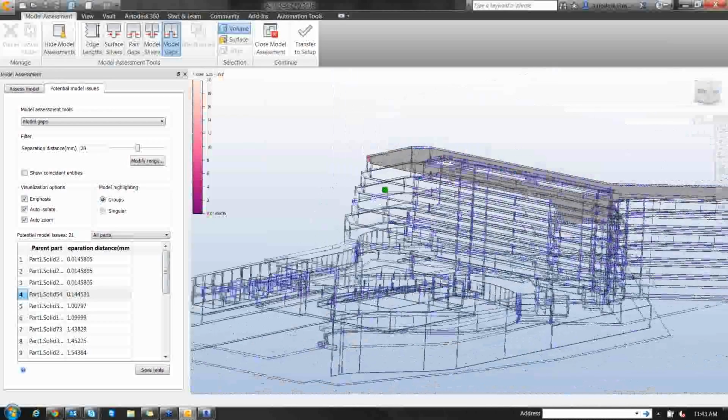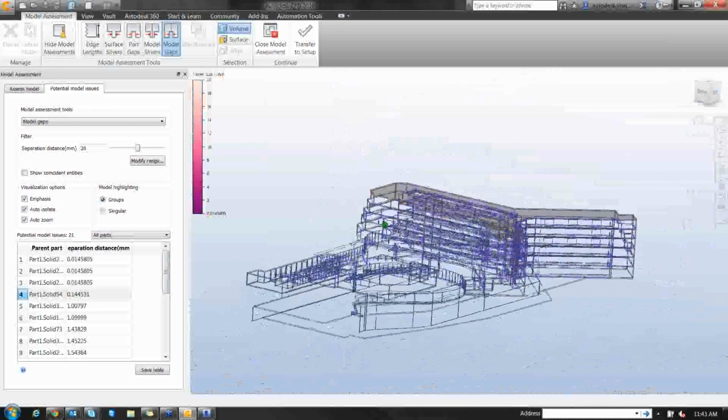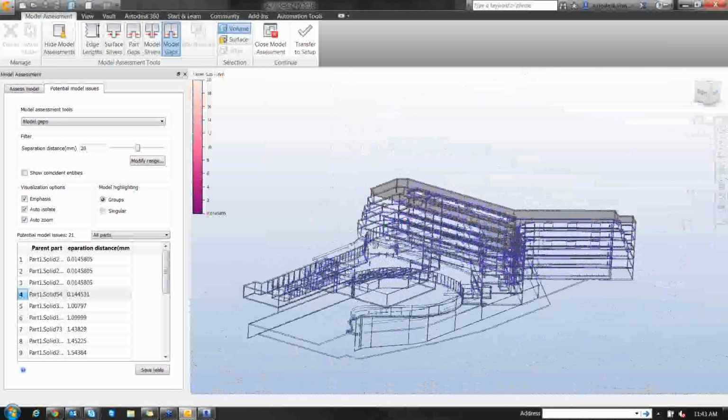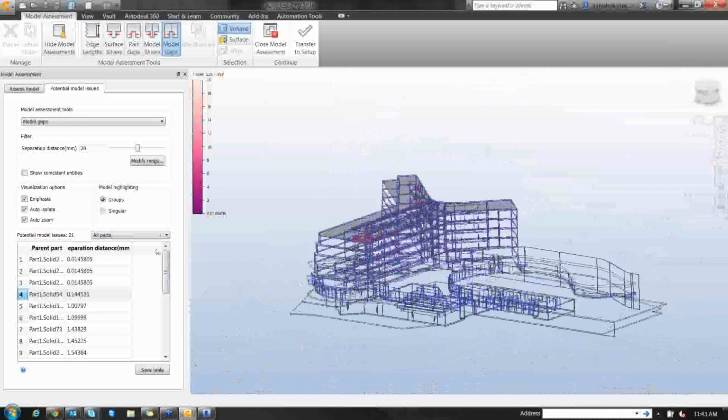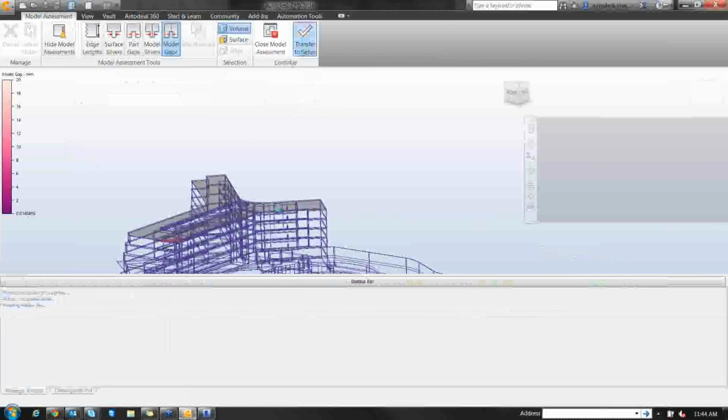So, anyways, I just encourage you. Maybe you'll get a crazy nodal aspect ratio if you're lucky. Yeah, that's probably what I'd end up having to do, if people aren't familiar with that trick, is basically turn off mesh enhancement, and I don't know how long this will take to transfer, but if you turn off mesh enhancement and turn on the stream function result, that enables nodal aspect ratio for a 3D model.